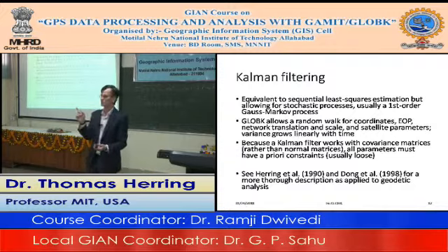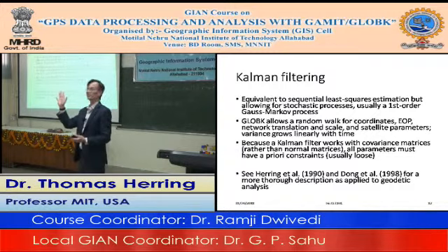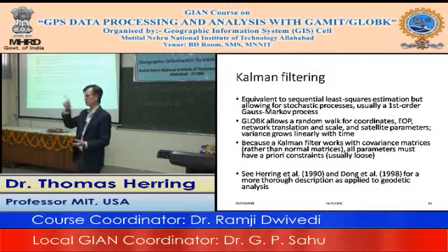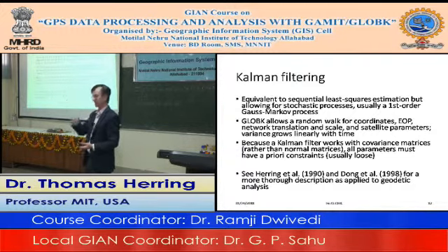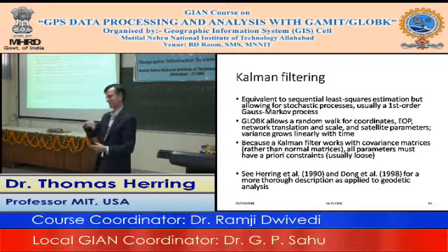Any of you who have done precise leveling, so anyone done precise leveling or learned about precise leveling? Okay, only one. Anyway, there the standard model is square root of distance, right? Yes. And that is a random walk. That's the same model in precise leveling, except there it's not time, it's in how far you go. Every measurement you make has a random noise, and that will grow.